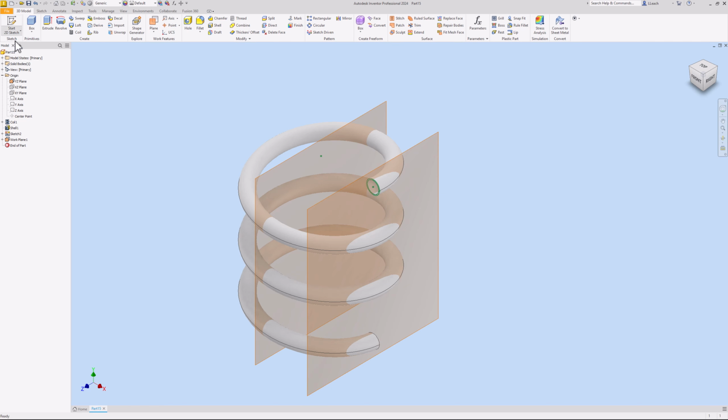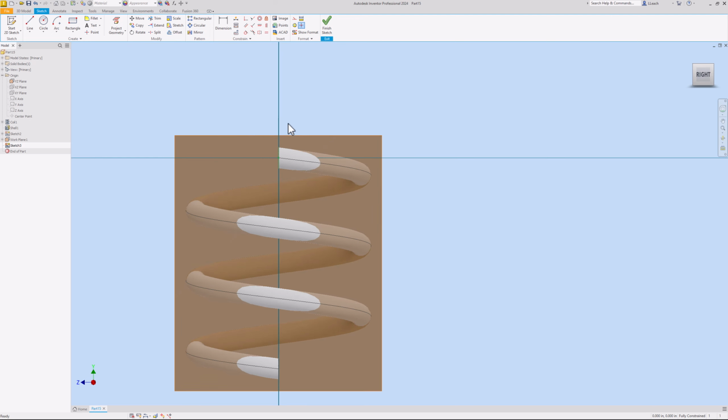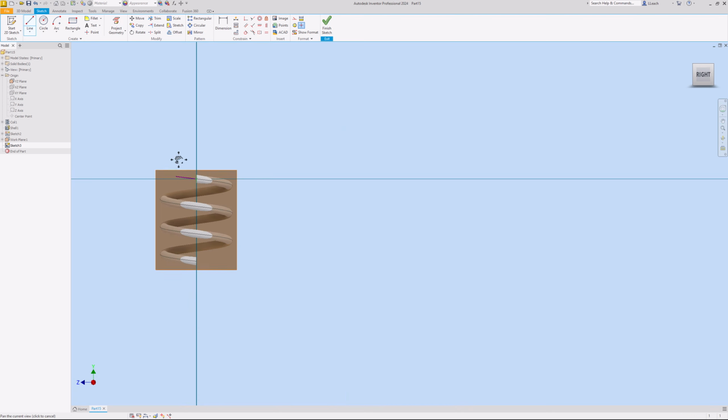So I'm going to start my 2D sketch on this plane here. I'm just going to draw a line from that dot. I'm going to drag it up a little bit angled, to match what we have going on with the end of our straw here. So draw it angled up a little bit, and then maybe draw it up about, I don't know, 3 to 4 inches, roughly. I'll say right there. Right click, hit OK.